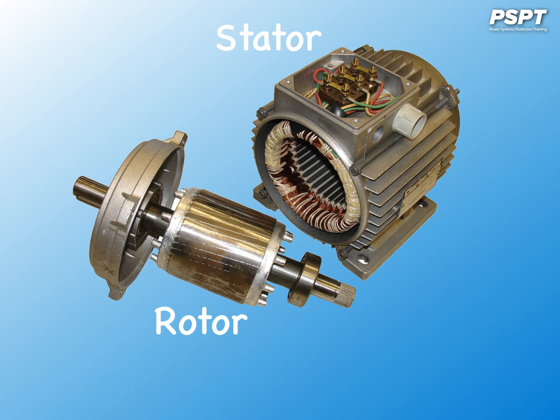The rotor winding derives its voltage and power from the externally energized stator winding through electromagnetic induction, and hence the name. The induction motor may be considered to be a transformer with a rotating secondary, and can therefore be described as a transformer type AC machine in which electrical energy is converted into mechanical energy.